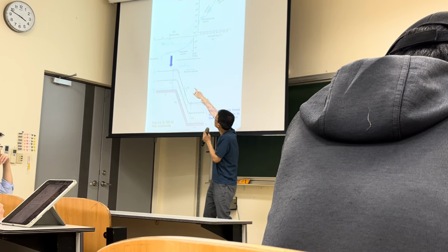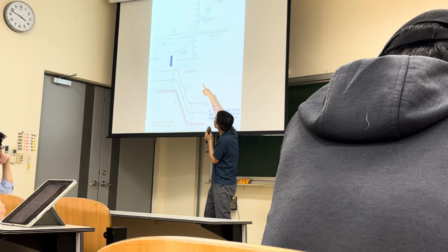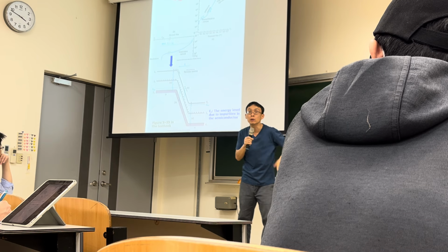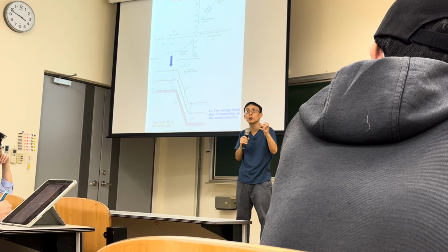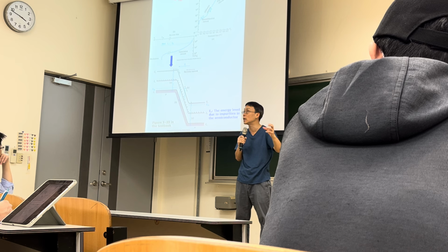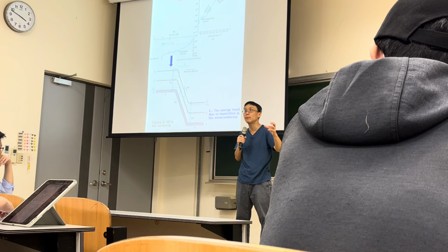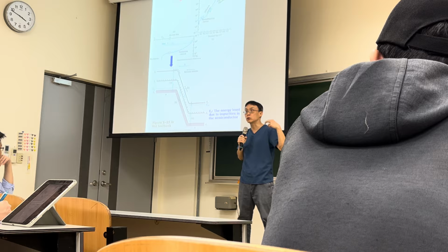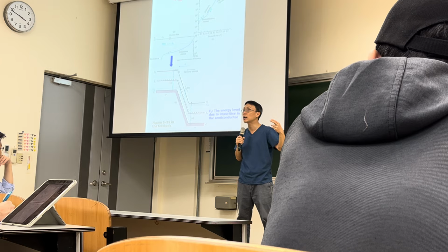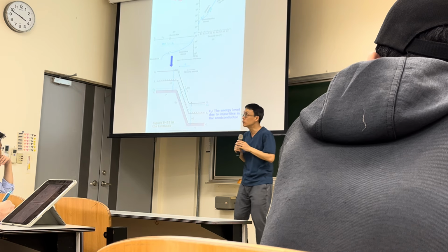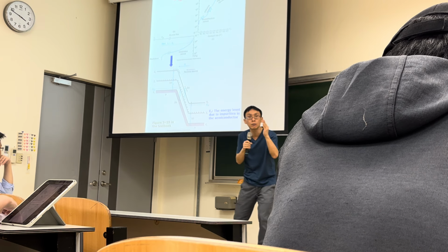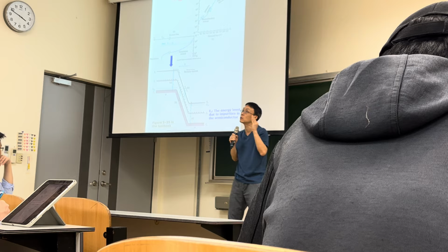So what we see now in the negative bias, the solid line versus the dashed line, is not avalanche breakdown. Avalanche breakdown is not reversible. Once it happens, it will never come back because you totally destroy the diode. But if you are only in the generation current at moderate reverse bias, this is reversible.